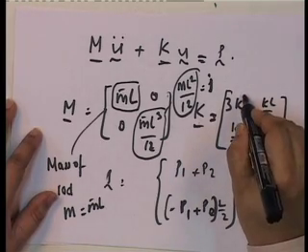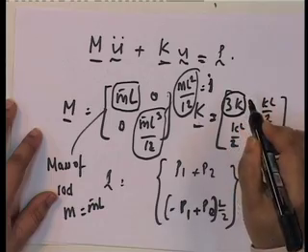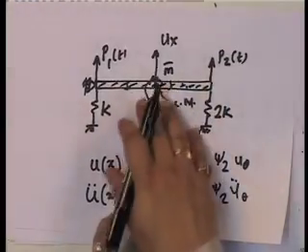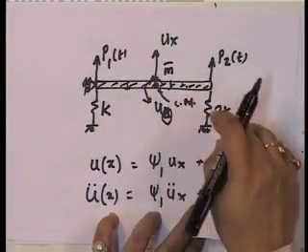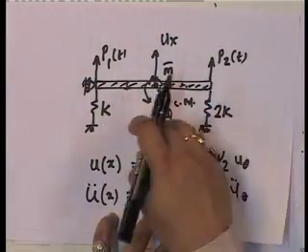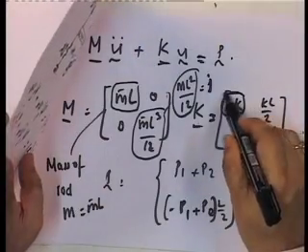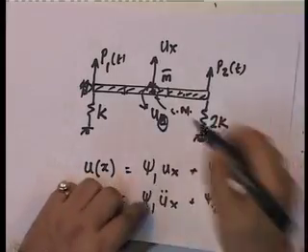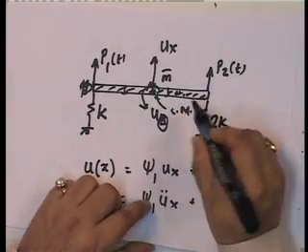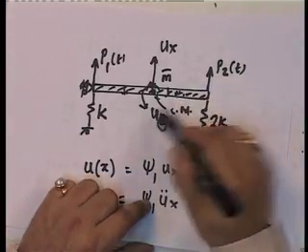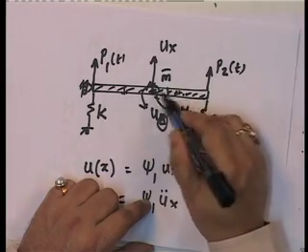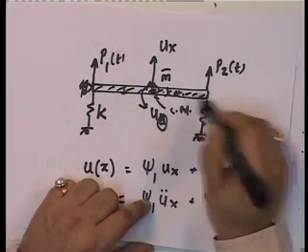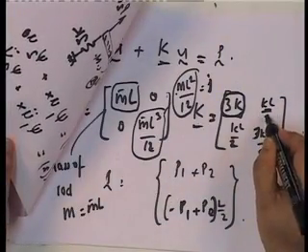If you look at this, what does this represent? If I were to give it only a uniform displacement, these k plus 2k would add up, and this is what you have here. Whereas, if this is the center of stiffness, the net stiffness is 3k, and this distance is L upon 6, so 3k into L upon 6 is kL upon 2.